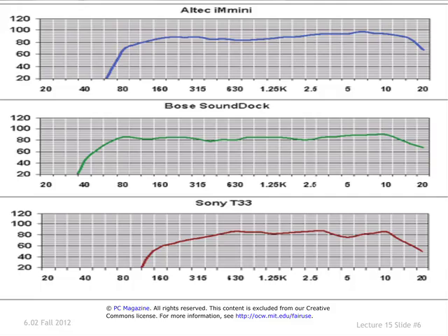And then we talked most specifically about a physical medium that's close to what you're doing in the lab, which is the medium of, well, an acoustic channel driven by a loudspeaker, and at the other end a microphone to pick up the signal. And I showed you these typical characteristics of loudspeakers, the kinds that you'll find listed everywhere, 3 different speakers. I mentioned last time that when you look at frequency specs for speakers, people will typically only show you the magnitude specification, because for audio applications, the phase distortions are a little less important. They tend to not be picked up by the ear.